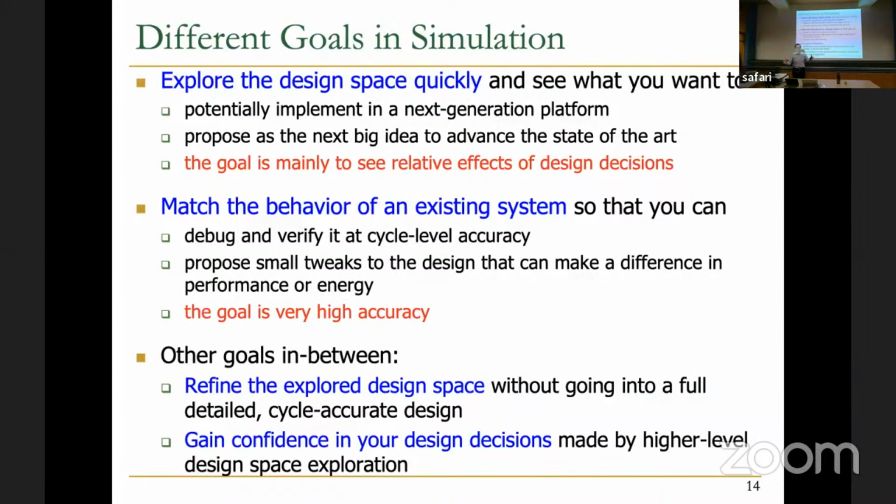Essentially, what happens in system design today is you start with a very high level simulation, and then you refine things with lower level simulators. And eventually you have a simulator at the gate level that hopefully matches the behavior of the next generation system. But you can actually inform that simulator based on the current generation system that you have also. So you can calibrate your simulators. And then once you actually implement the hardware, what you have is something golden: you have all these simulation levels, simulators that you developed. You can calibrate all of them to the actual hardware, right? And the lowest level simulation, even the Verilog simulation, has some error compared to actual hardware. This is actually consistent. In many places, usually that error ranges from 0% to 5%, sometimes even 10%, because what you do in Verilog is not exactly what's implemented in the chip, right?